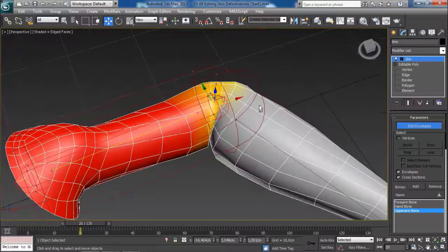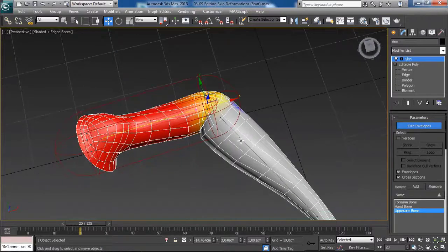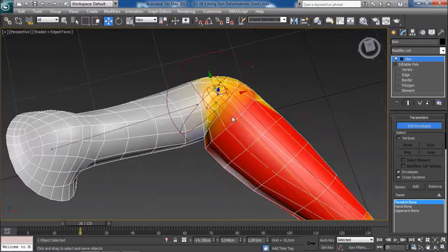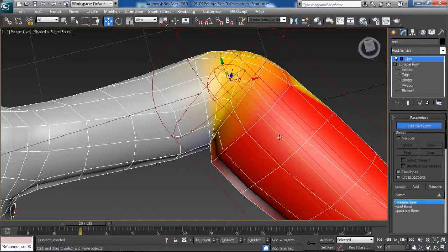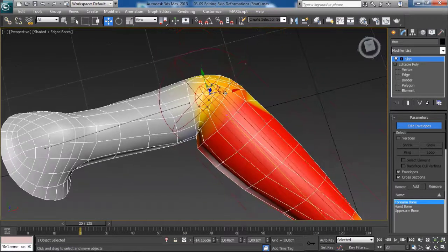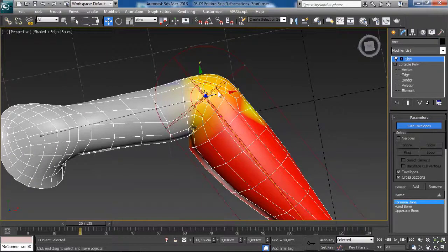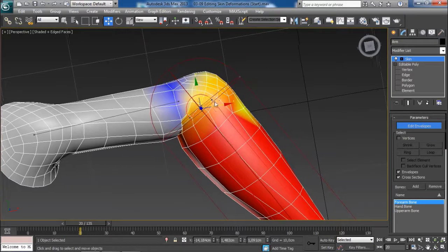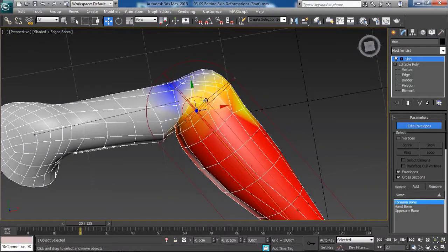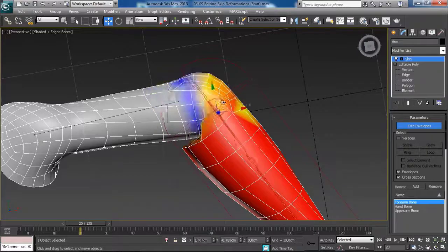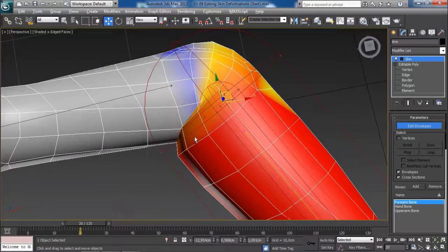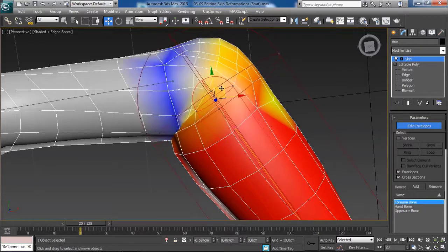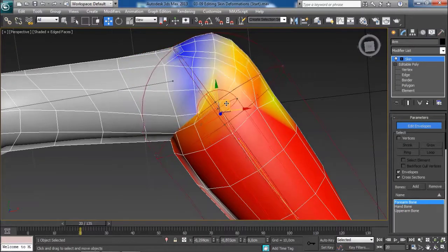Okay, this looks beautiful. Let's go ahead now and fix the forearm in the same way. We'll first select the forearm bone by selecting the line that represents it. Again, we want to select that endpoint, this one over here, of the yellow line. And now we can start moving this to the back. And take a look. We are now getting different results. We can continue to adjust that until we remove that gap entirely. Okay, let's continue doing that. Let's move this just a little bit to the back.